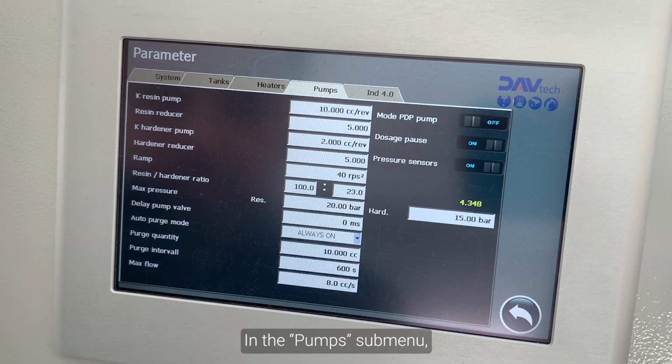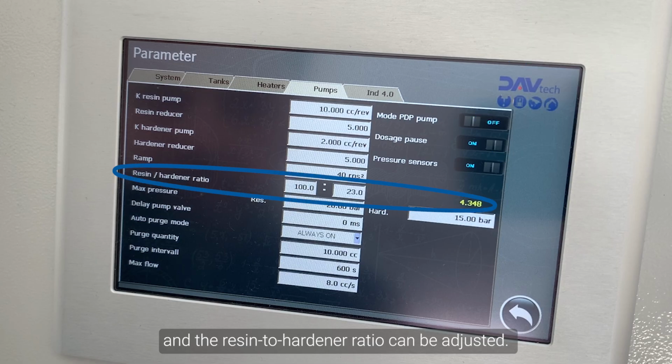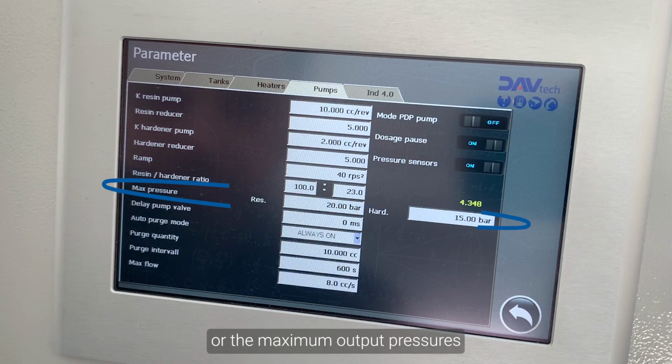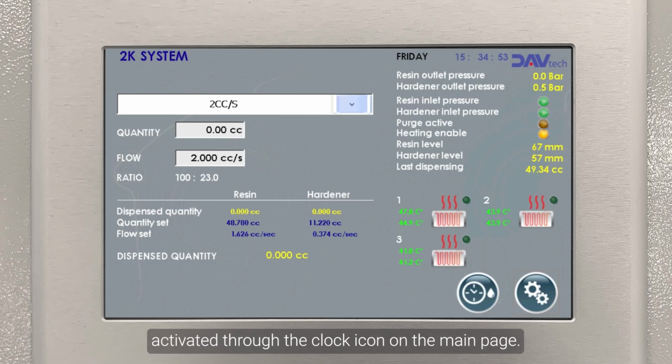In the pumps submenu, the parameters for volumetric pumps and the resin-to-hardener ratio can be adjusted. The end user can modify the resin-to-hardener ratio in case of resin change, or the maximum output pressures of resin and hardener. It is also possible to define the quantity and frequency of the automatic purging, activated through the clock icon on the main page.